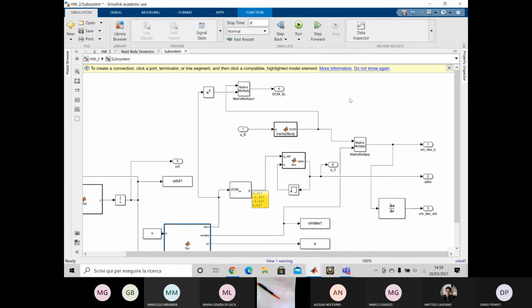Yeah, the more I think about this, if I want to go from my body axis aligned with the inertial basis to something that looks like this, I don't know how I can visualize it. It's going to be some strange angle and some other axis pointing in space. But a quaternion that has multiple components like this sounds more meaningful, because you can't visualize a rotation that goes from these to these about just one of the coordinate axes. It's probably a more complex rotation if you want to represent it as another axis and then an angle about that axis.